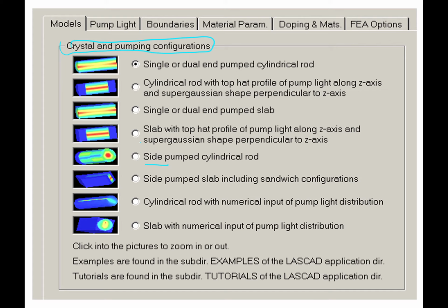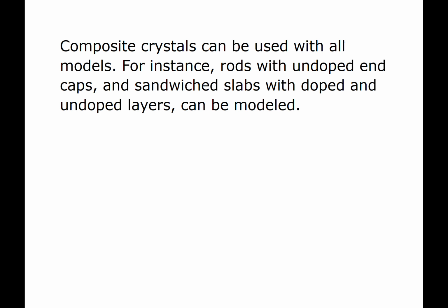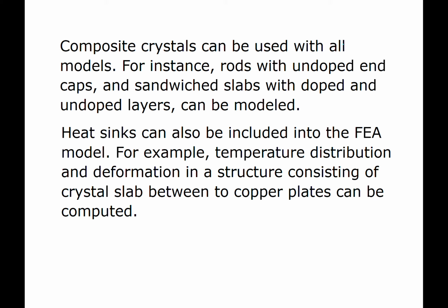Okay. And then here you can choose the pump light condition, boundary conditions, material parameters, pumping materials, and FEA options. You can have a mesh, very small meshes, or optimal mesh, or larger meshes. Composite crystals can be used with all models, for instance, rods with undoped end caps. Sandwiched slabs with doped and undoped layers can be modeled, and heat sinks can also be included, which is very practical.